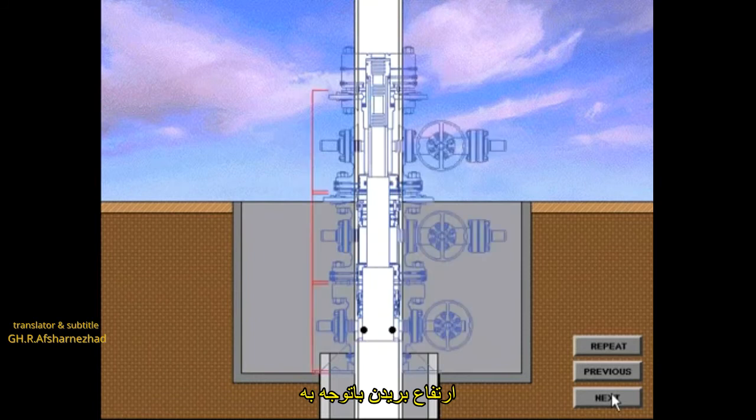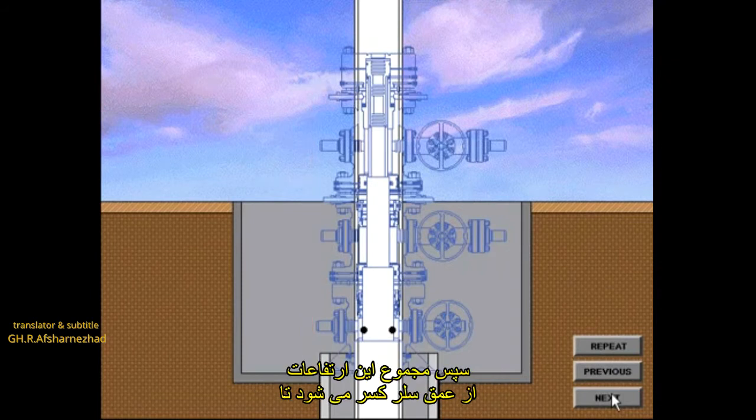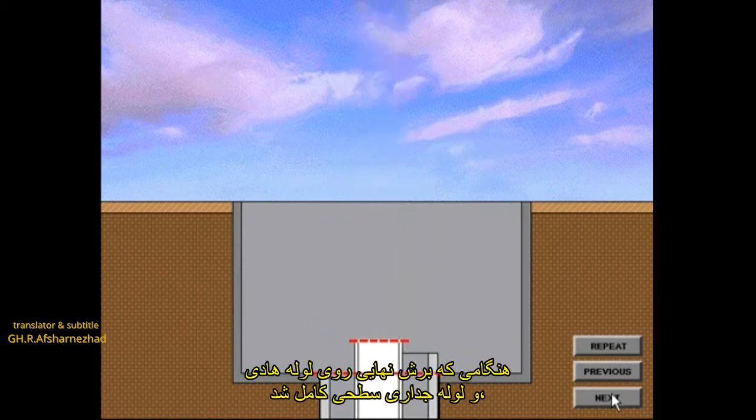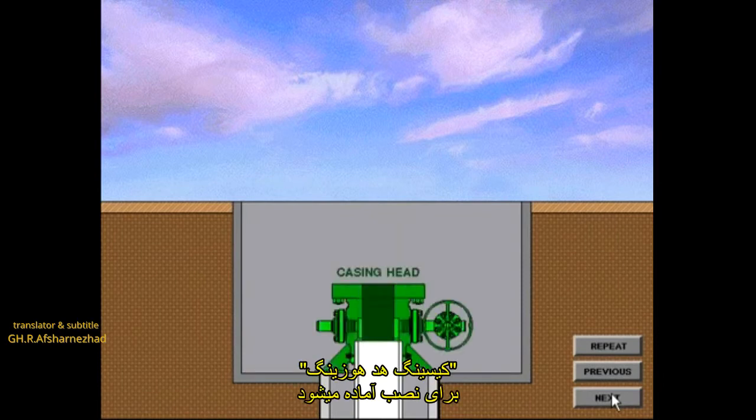The final cutoff height is determined by adding the height of each piece of wellhead equipment plus the standoff distance between each piece of equipment and the ring gasket height. Then deduct the depth of the slip-on socket in the bottom of the casing head housing. If a base plate is used, its height must also be considered. The sum of these heights is then deducted from the cellar depth to determine the final cutoff height for both the conductor pipe and surface casing. When the final cut on the conductor and surface pipe is completed, the casing head housing is prepared for installation.